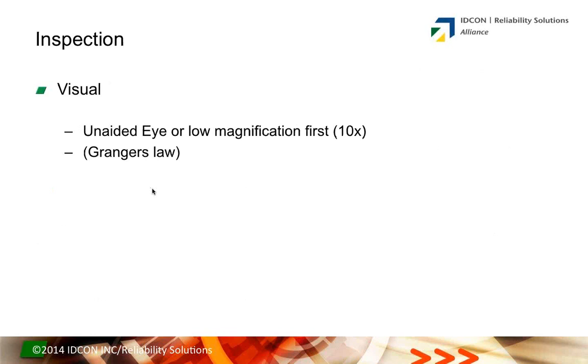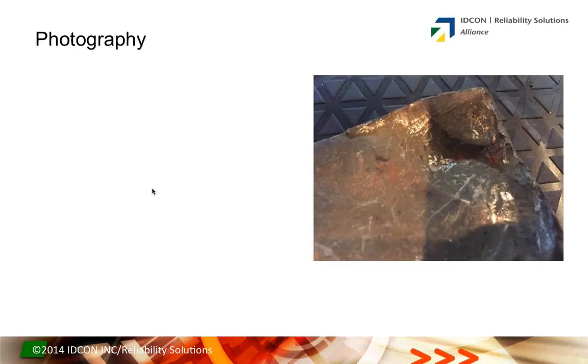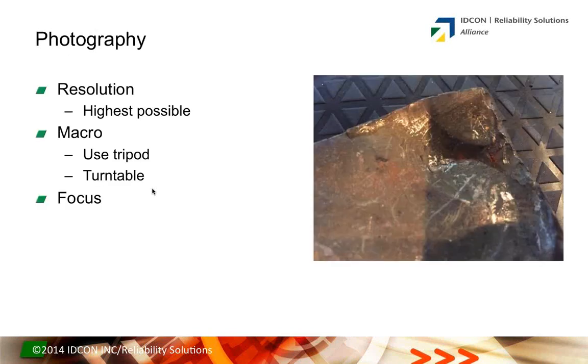In terms of inspection, again, inspect with either the unaided eye or no more than a 10-power magnifier. You can pick up that little loupe from Amazon for 20 bucks or something. 90% of everything you do in looking at fracture faces and failed parts, 10 power is all you need. When we're talking photography, nowadays, a couple of tips. The sensors on modern smartphones are of such good quality now that you don't need a high-end digital SLR, so long as you light it correctly.